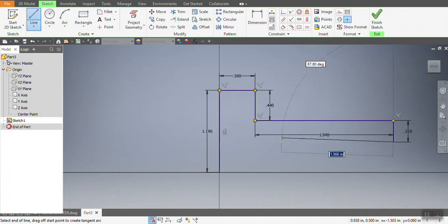I'm moving left. This time I don't need to enter dimensions anymore, because this software, Inventor, understands the location of my cursor. When it is lining up with the previous point, it shows me with dotted lines. That means I don't need to enter dimensions anymore. Because it shows me with dotted lines that it sees the earlier point, the location of my cursor is directly, perfectly matching the location of the previous point. So I click, okay, move my cursor, and the same thing happens. When it lines up with the 0,0 point, it shows it to me.